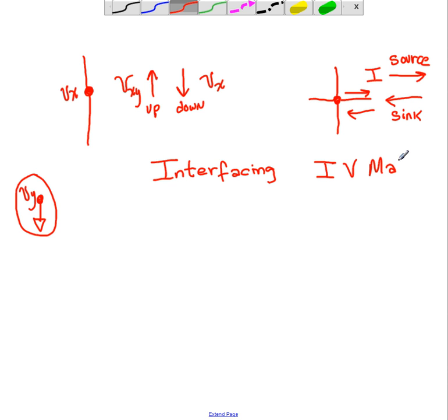For every point in your system, for every component, device, or module, you need to be very clear about the IV matrix range for that point. Usually you get this information either from experimentation or by studying the details of the data sheet.